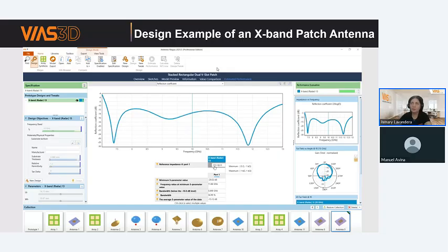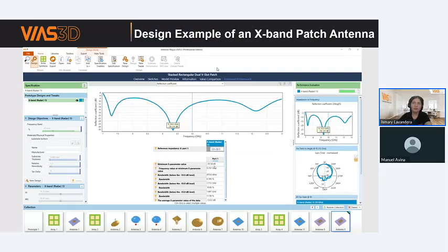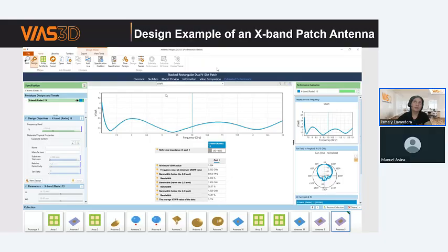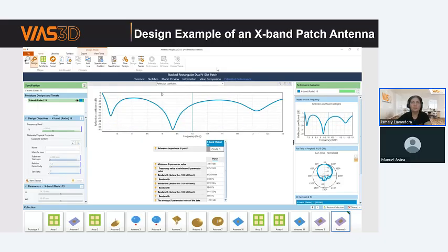If you see the impedance, there is 72, so this design was designed for 70. And for my specific system, I want 50 ohms. So I want to see how the reflection coefficient would look like. So it seems that I need to improve a little bit the matching of my antenna. So I'm checking the VSWR, the impedance, reflection coefficient.